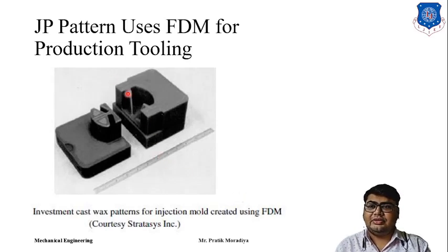Another company, JP Patents, also used FDM, and they used it for creating an investment cast wax pattern. So they created an injection mold using FDM, and then from that mold they created wax patterns, and from that wax pattern they created the actual parts.